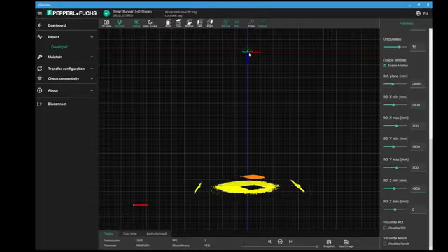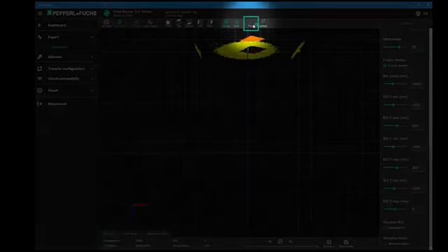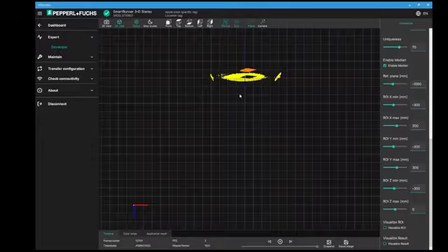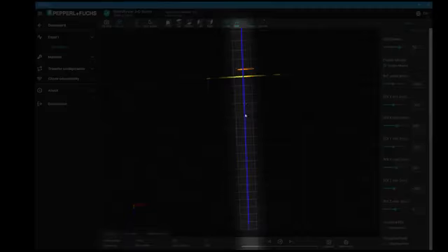We have a right-handed coordinate system. X and Y remain in their orientation, but since we're shifting it downward, we shift it to minus 1.6 meters relative to the camera. We've specified that here. Now, when we switch the coordinate system to the reference plane, you can see, illustrated here with the blue and red lines, that the reference plane is at the origin.